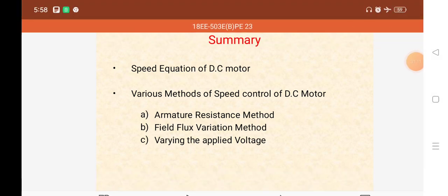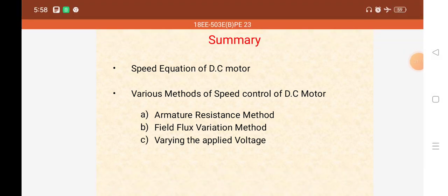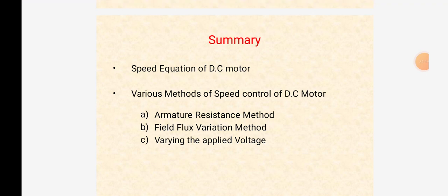Here we have the advantages of thyristor control drives, that are the drives are higher accuracy, exact desired speeds can be achieved, it is the greater flexibility and greater reliability, higher efficiency of operation owing to absence of moving parts and I square R losses, ease of maintenance, low installation cost, lower floor space is required, it's also soft start and reduced mechanical stresses, energy saving is more.